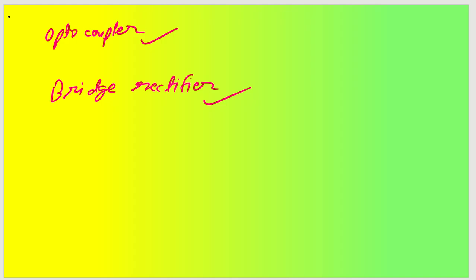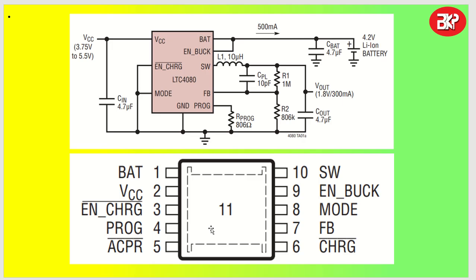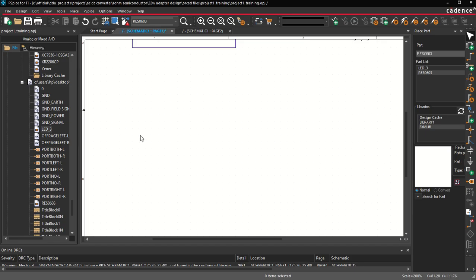So what I will do is I'll try to develop this particular IC which is there. For that I need to have an understanding of how to make this particular symbol and name all the pin numbers. So for that, what we have to do is open OrCAD.